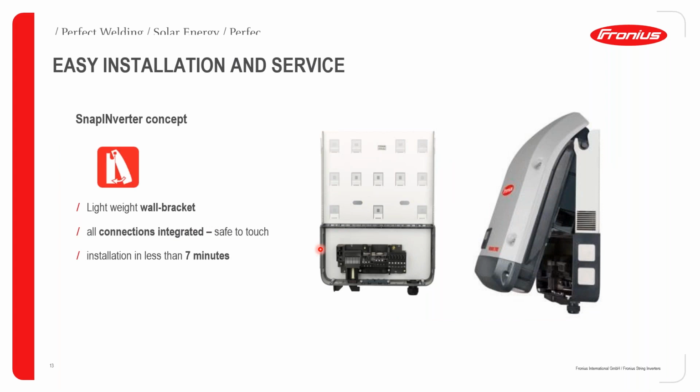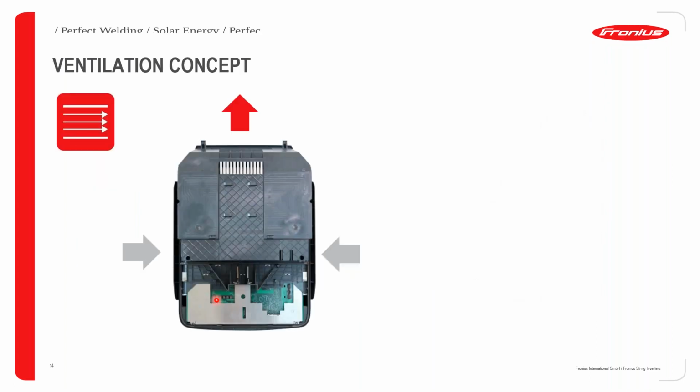Our Snap inverters come with what is called the Snap inverter concept. That's really where the name comes from. Snap stands for the method in which the inverter is installed onto the backplates. As you can see, the front of the inverter, where all your power electronics is, is basically snapped onto the backplates. You can also see that all your AC and DC connections are integrated on the backplates. So this will really allow for fast and quick installation as well as service.